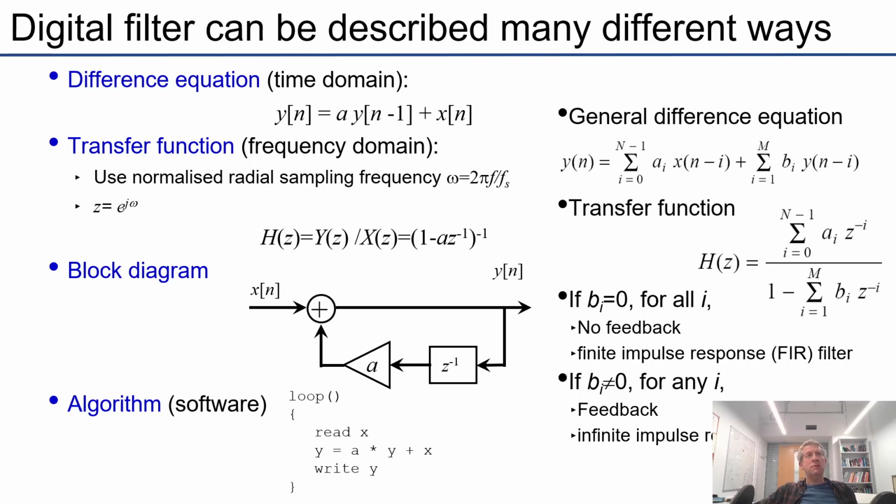There are plenty of uses of high order FIR filters. FIR means finite impulse response, so there's no feedback, and that includes reverb, where models of reverberation might have hundreds or even thousands of filter coefficients, but it's all feed forward. Generally, people rarely design very high order infinite impulse response filters, the ones with feedback, because those are more likely to have issues with boundedness and stability.